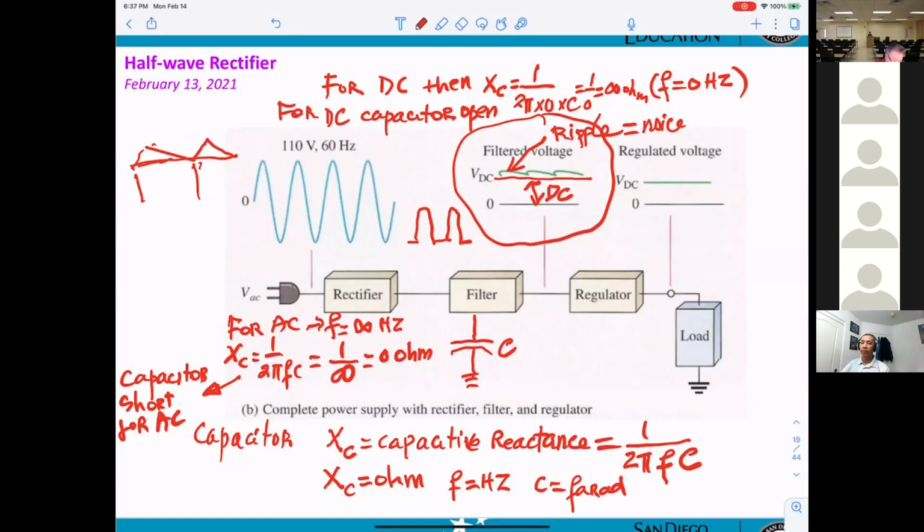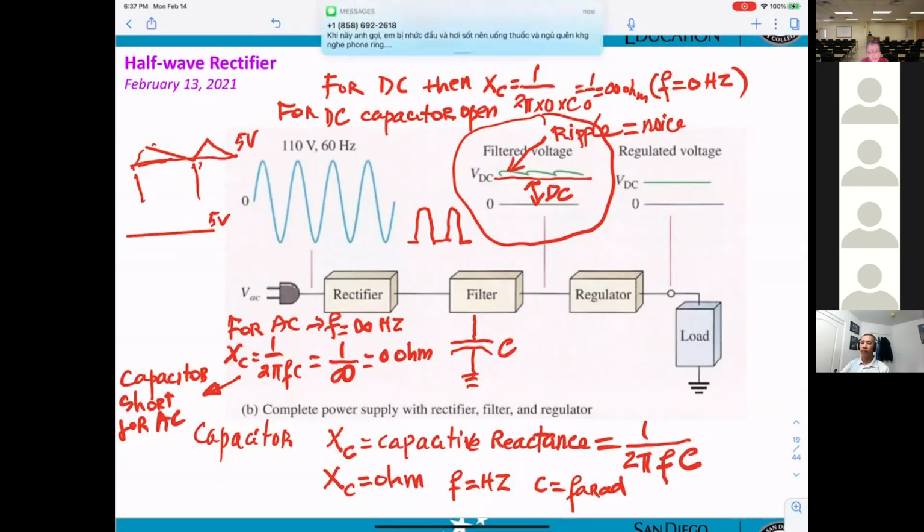The thing is, if you get 5 volts, you want the 5 volts just straight. No signal on top, no noise. That noise can cause parts of the circuitry to not work. Like when you're working on digital circuitry, you take the input, everything is good, however the output is not coming out like you wanted. That will be telling you you have noise.